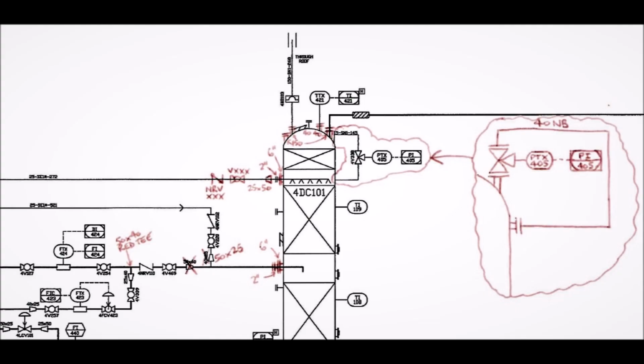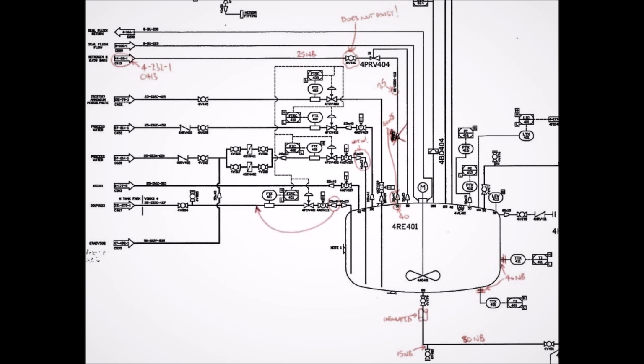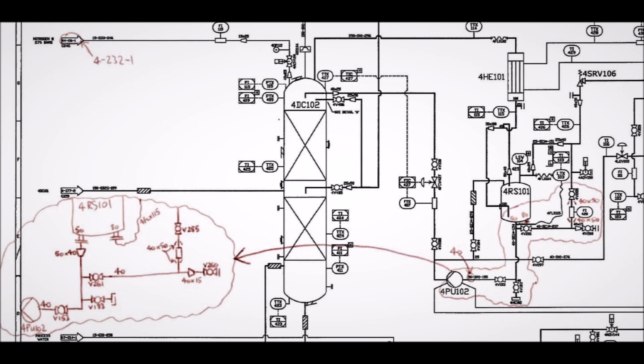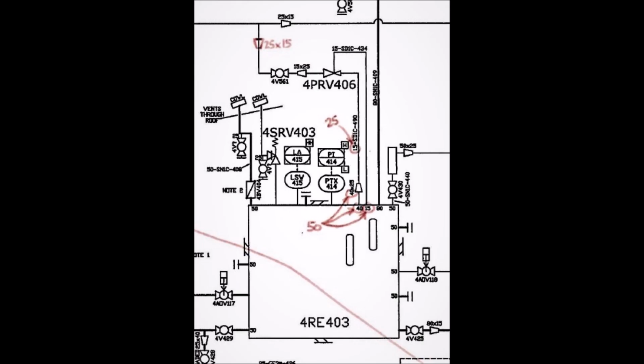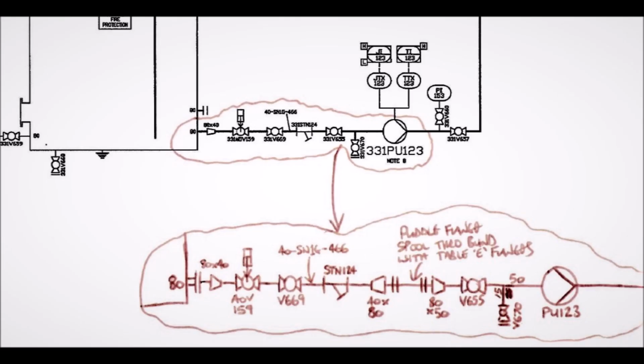Dispex project. For this project, a number of new inline items were required, as well as a replacement of existing with safety upgrades. A site survey revealed many errors, incorrect line sizes, specs and additional items, but the P&IDs had not been updated to show these changes. As previously shown, the ISO layout is able to resolve all issues to correctly identify the full scope of work required, correcting P&IDs before contractors were engaged.